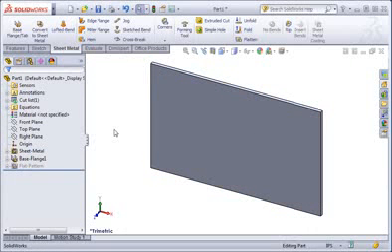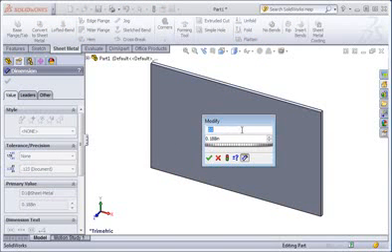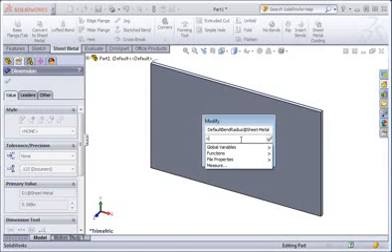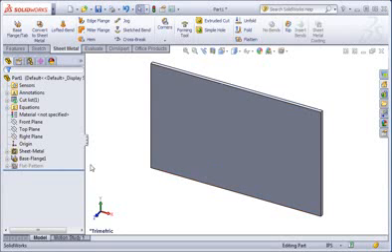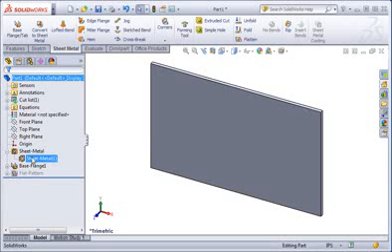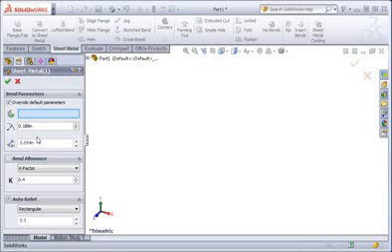We're also going to set the bend radius to 2 times the wall thickness, so select the sheet metal folder, and then double-click the dimension. Name it default bend radius. And in the value cell, type the equal sign, select the thickness, and make it 2 times the thickness. Now expand the sheet metal folder, and then edit sheet metal 1. Uncheck Override Default Parameters, and then click OK.